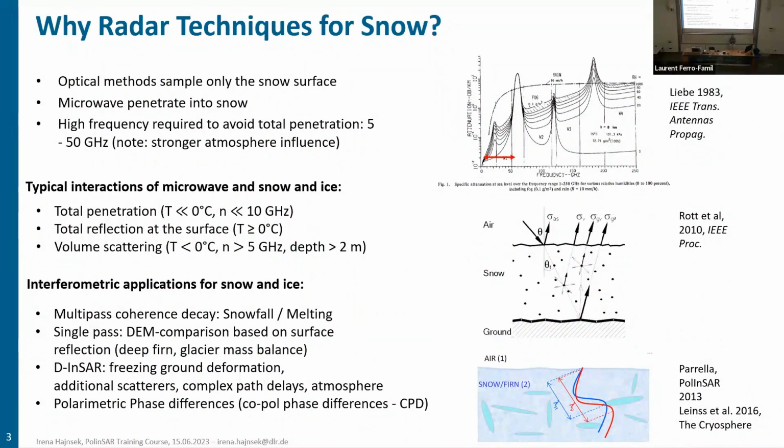In the higher frequency range that we have, which can be from P-band with wavelengths of around 80 centimeters until X-band, which is the usual distribution of wavelengths that we have. So P, L, S, C, and X-band. These are the wavelengths that we use, and these are all in the range that you see here, for example, between around 600 or 800 megahertz until 50 gigahertz. So this is the frequency range we have. And this means we have wavelengths from around 80 centimeters to 1 centimeter or even a little bit less.